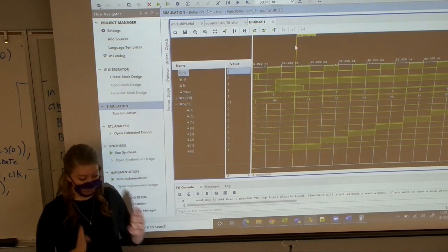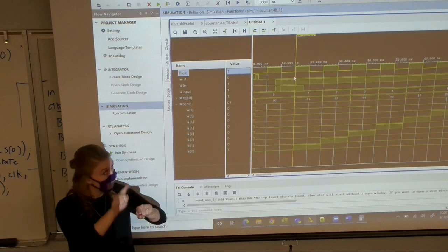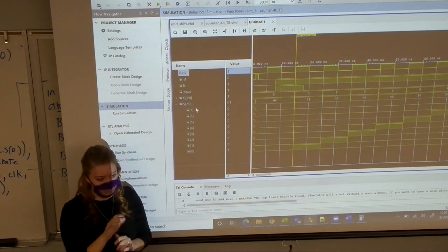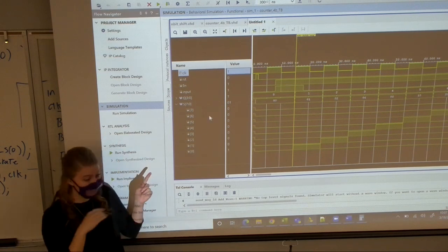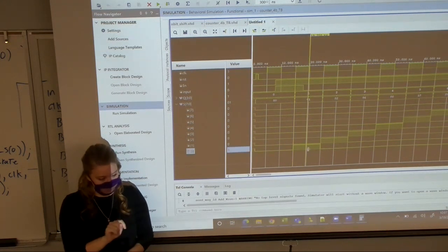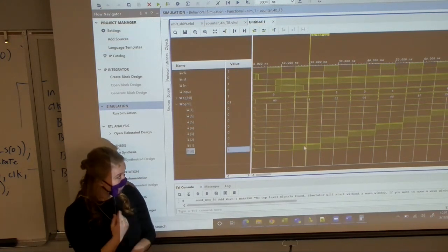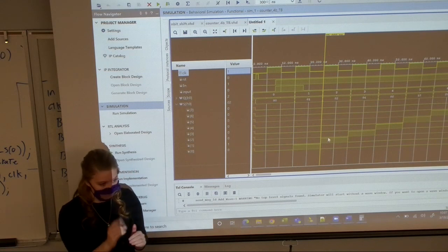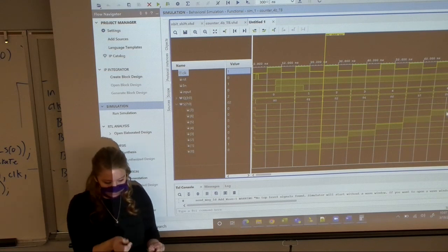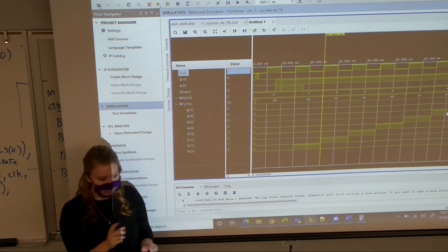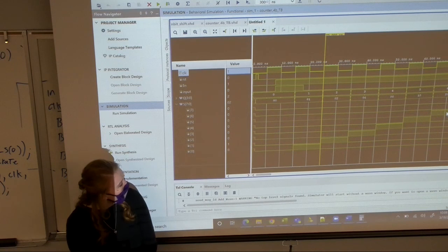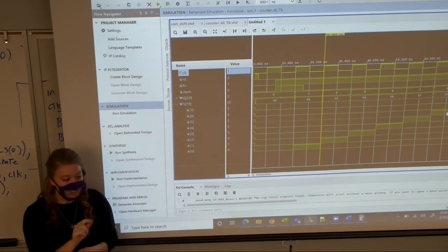So that rising edge of the clock, where this yellow line is, triggers the first shift register, bit 0. And you'll notice that there are 8 bits, because I said it was an 8-bit shift register, to clock in that first one. And then bit 0 gets clocked in as another 0, because 0 is the input. But we get to see that march through that shift register. Anyway, that's shift registers, generics, and generate statements.